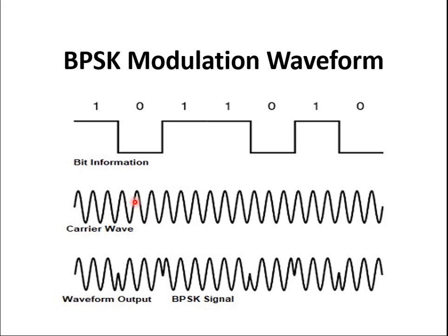You can observe that whenever there is a transition from 1 to 0 or 0 to 1, a 180-degree phase shift happens. You may ask why only 180 degrees. Don't worry, my input signal has only two possibilities, logic 0 and logic 1. If my input signal had more than two possibilities, like 00, 01, 10, 11, the phase shift would be different. Why 180 degrees?